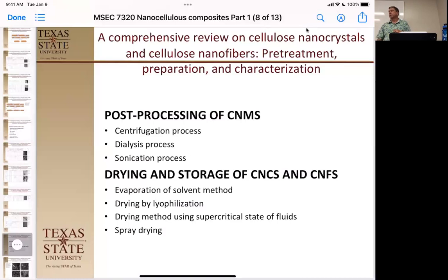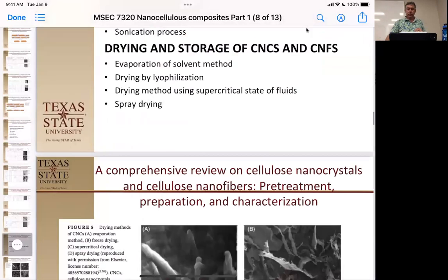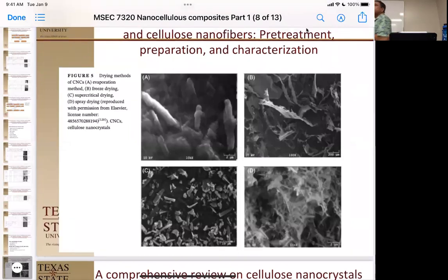The last one is on production and costs. So at industrial scale or large scale, is the sonication process preferable, or is it applicable? No, because it's hard to get. See, if you have just a little sample and a little tip, you can get like 500 watts in that little section. If you're doing a flow process, you have to have the entire flow process under sonication. And once you start getting into 500 and 1,000 watt sonicator modules, those are like $5,000.